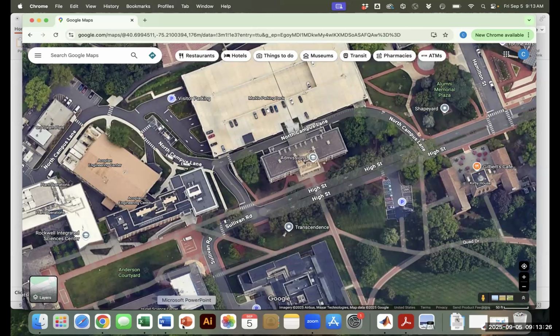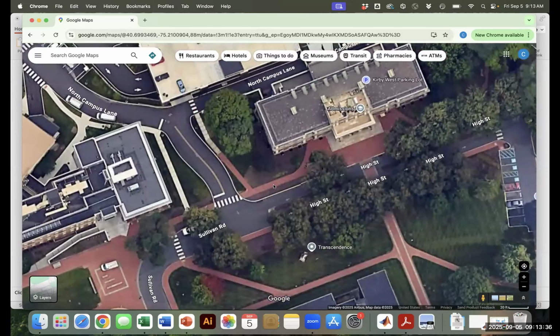And as you're doing this, you're probably going to want to do a little drawing on a piece of engineering paper and just note those distances in feet. For this particular building, I would probably measure the width of the road. I'd probably get some information about the sidewalks. Again, I'm just looking for rough dimensions that I can translate into Civil 3D.